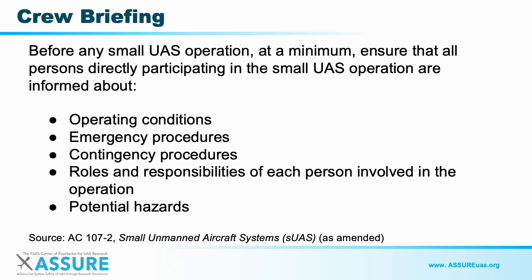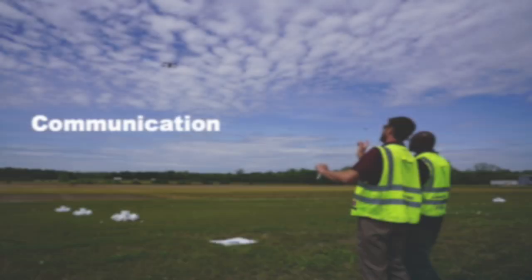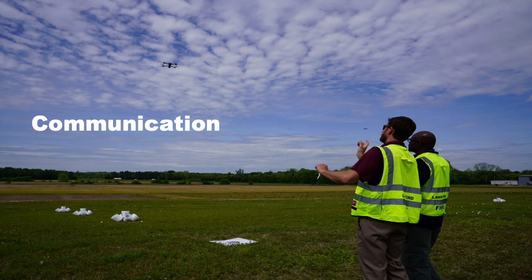A crew briefing is likely something you have heard about as a best practice. Before any drone operation, at a minimum, ensure that all persons directly participating are informed about operating conditions, emergency procedures, contingency procedures, roles and responsibilities of each person involved in the operation, and potential hazards. Now we'll spend some time discussing communication.